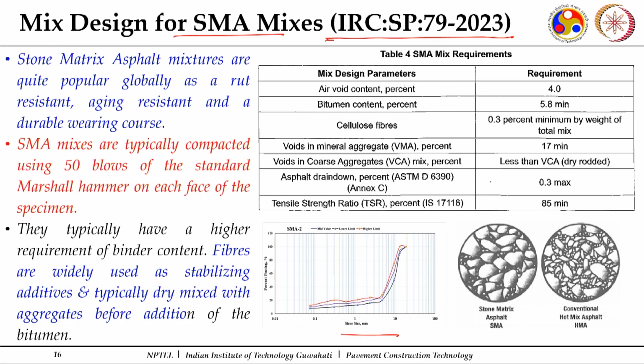and then a coarse aggregate skeleton is there. So a stone matrix skeleton looks in this manner compared to the conventional dense graded bituminous concrete mixes. Here you can see the proportion of larger, coarser aggregate particles is more, to bring more contacts between larger aggregate particles for a better load dispersion and a greater strength.